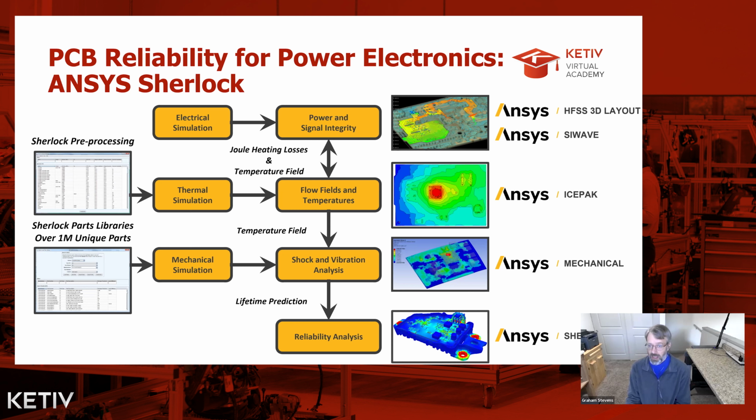which then allows you to estimate the mean time between failure for the entire board. And then I might pick different analyses and say, I want to dial in on doing an electrical simulation to get a little bit more accurate on the current that's actually impacting this aspect of the board, or look at the flow fields and temperatures, or look at shock and vibration analysis. And so then you can do those FEA simulations and integrate the information from those back into Sherlock and get more accurate estimates of total reliability. So just wanted you to be aware of this package and its capabilities.